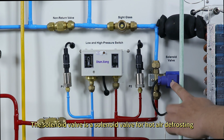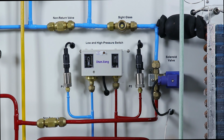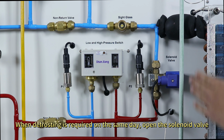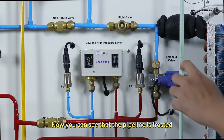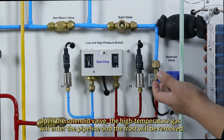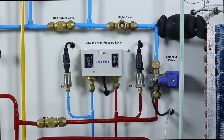The solenoid valve is a solenoid valve for hot air defrosting. Usually, this is the disconnected state. When defrosting is required on the same day, open the solenoid valve. Now, you can see that the pipeline is frosted. Open the solenoid valve, the high-temperature gas will enter the pipeline and the frost will be removed.